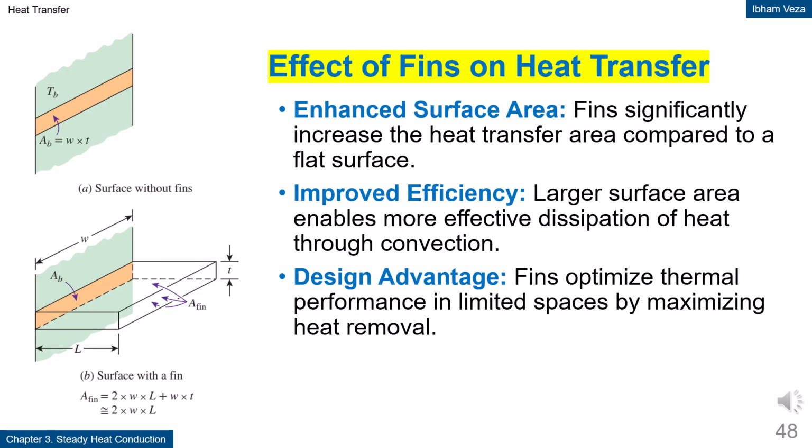Effect of fins on heat transfer. Adding fins significantly increases the heat transfer surface area. With a larger area, heat can be dissipated more effectively by convection. This improves thermal performance without increasing the operating temperature. Fins become an efficient solution to enhance cooling in limited spaces. This principle is widely used in many cooling systems.